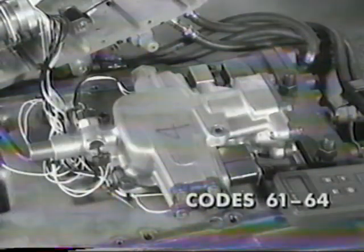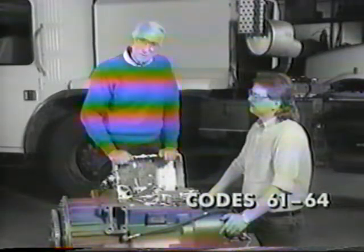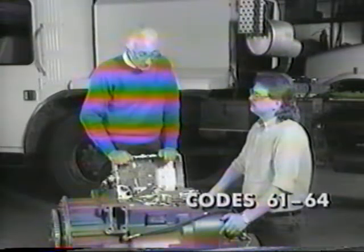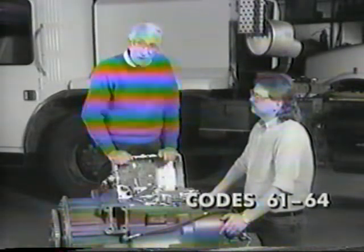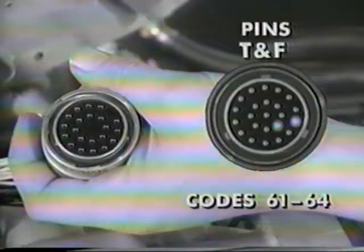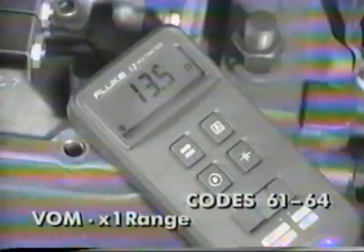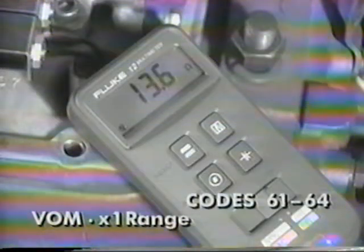The 4 60 series codes test the 4 auto shifter solenoids. The solenoids control air pressure to move the shift finger. Again, except for pin numbers, the procedures are the same for all 4 solenoids. So, to diagnose any of the 60 series codes, locate the correct pins in the auto shifter harness. For example, code 61 uses pins T and F. The reading should be 11 to 16 ohms.